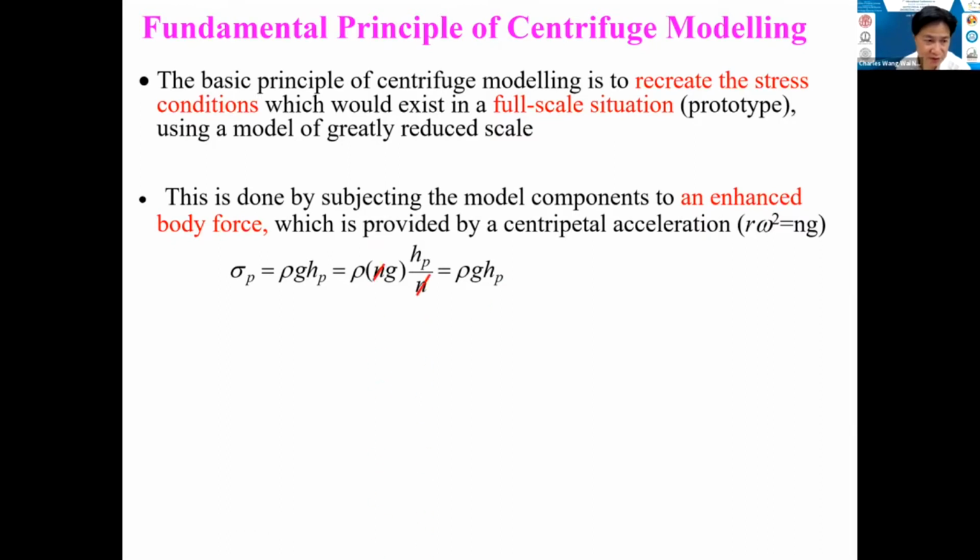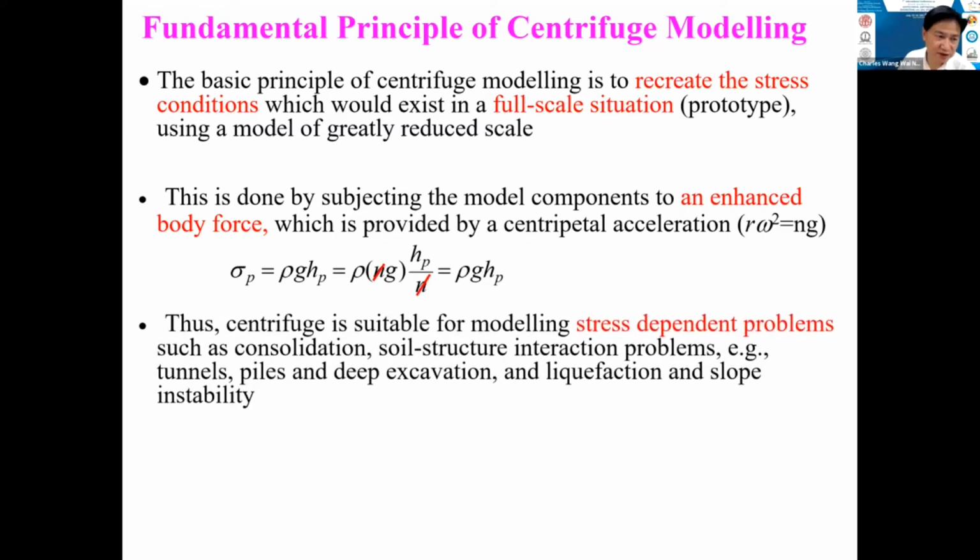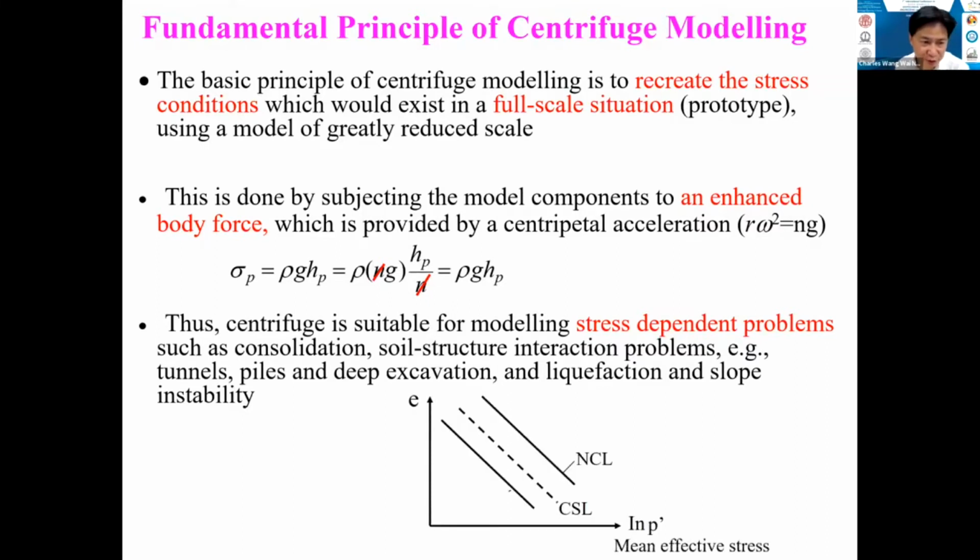Therefore, the centrifuge is suitable for stress-dependent problems, such as consolidation, soil-structure interaction problems, like the presentation given by Professor Aguma, soil-structure interaction subject to earthquake, and also liquefaction and slope stability, etc. Now, from a theoretical point of view, it's very, very important to get the stress right before we carry out experiments. Now, here's a plot of the e-log p curve.